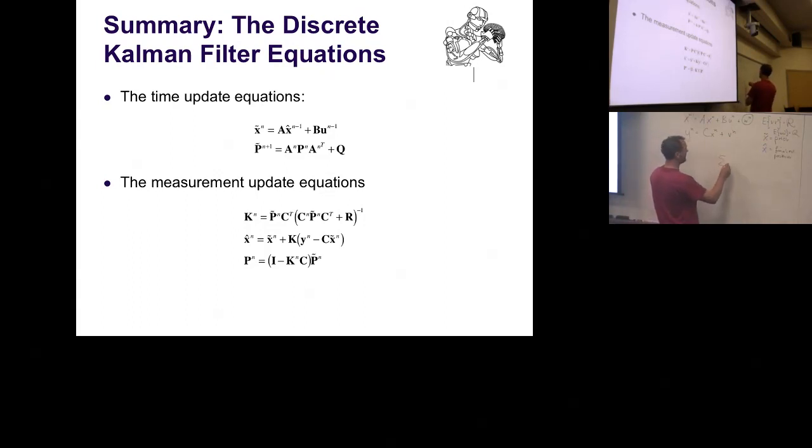You take the sum of measurements yi, with i equals 1 to n, assuming you get n measurements, so 1 over n. So this is going to be your mean. And then you compute yi minus the mean, squared, times 1 over n. And this is going to be your variance, which in our case would become your R. Okay? So this is using the physical process to measure things. It's a simple way of doing it, but it should normally do the job.